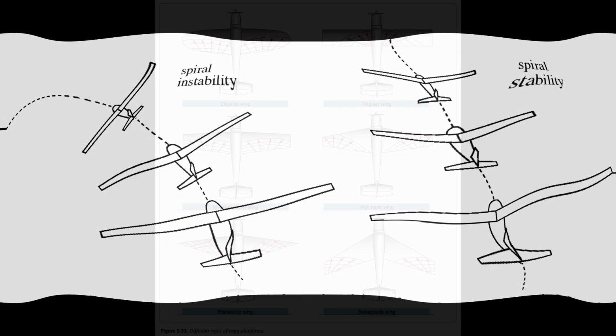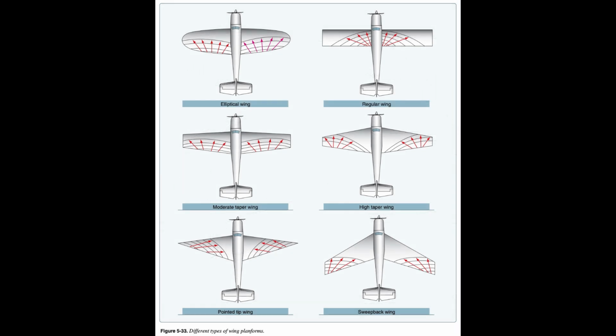Effect of wing planform. Understanding the effects of different wing planforms is important when learning about wing performance and airplane flight characteristics. A planform is the shape of the wing as viewed from directly above and deals with airflow in 3 dimensions. Aspect ratio, taper ratio, and sweepback are factors in planform design that are very important to the overall aerodynamic characteristic of a wing. Figure 5.33.